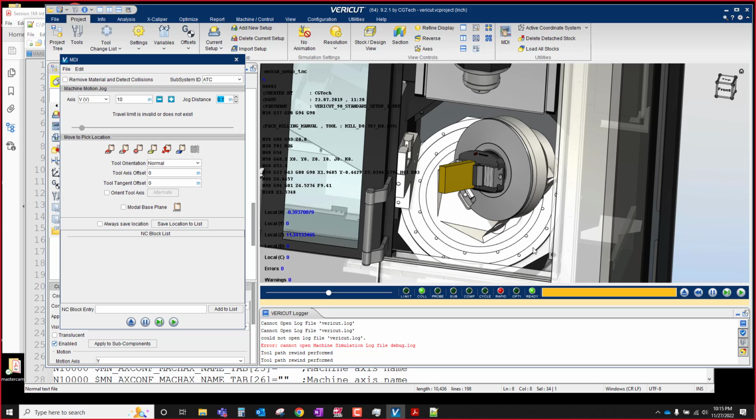One of the things I didn't mention in that conversation, and I'm not naming the name on the video, so I'm not too worried about it, was it would create this stock model of the as-built stock for the part, and it would ship that all off to Vericut. It would launch Vericut silently. It would run the whole simulation, and that worked in about 95% of the cases. It was completely automated: it scanned the part, made the tool paths, made the stock, simulated it. As long as everything was good, it would actually just run the part.